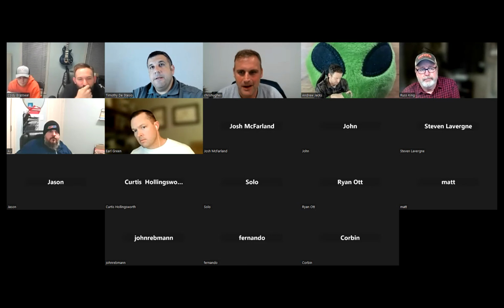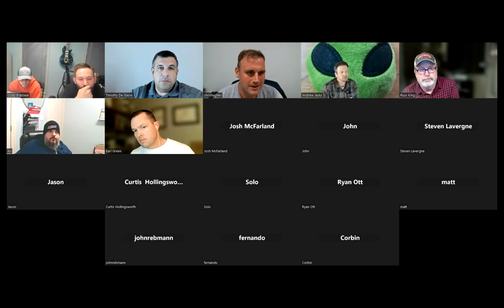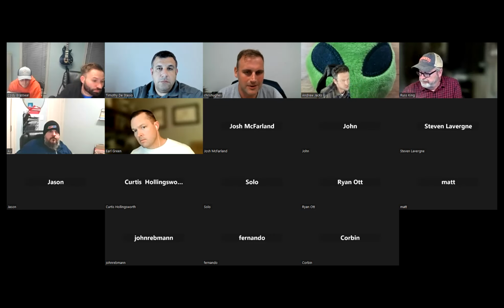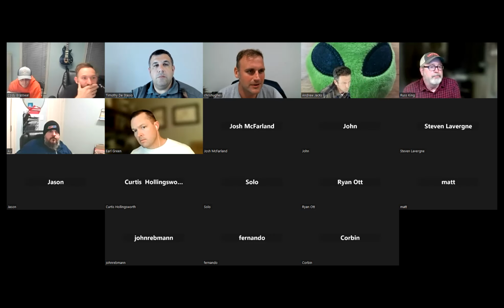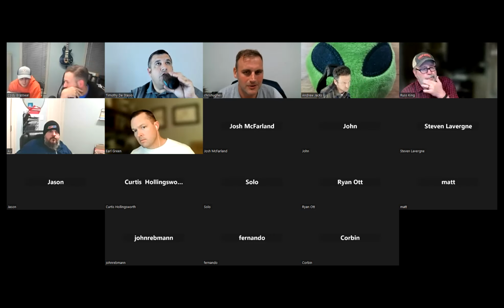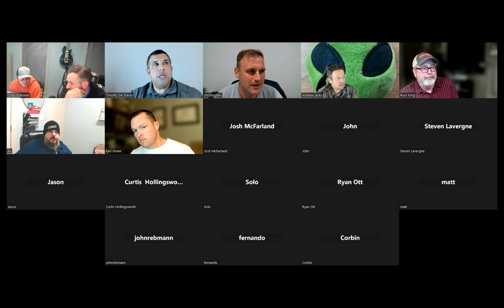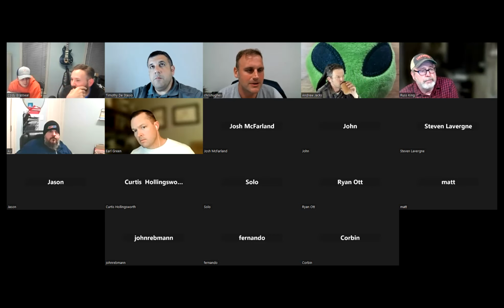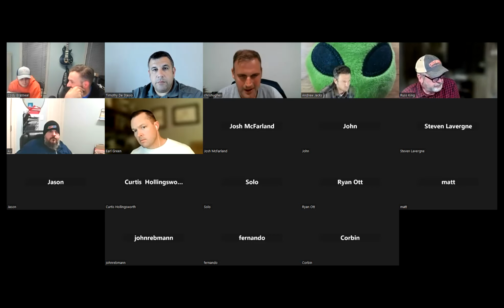Yeah. And I just want to reiterate what you were saying, Tim. Look, I'm not going to be the first one to bash. If what you have is a manometer, you've got to start somewhere. And that's the place to start. If that's what you've got in the tool bag, use that bad boy and start taking pressure measurements, go into the blower charts and start there. That's a great place to start. A few questions.